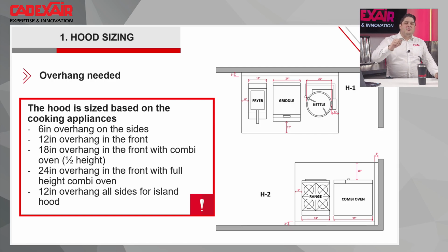Normally, people are supposed to open the door, and a lot of models have double action, and you're supposed to wait 5 or 10 seconds to let the smoke get out by the crack of the door. But I will say this is not what happens in real life. So if you want to have good control of the smoke, you had better get a good overhang over the cooking equipment.